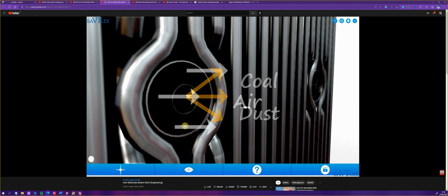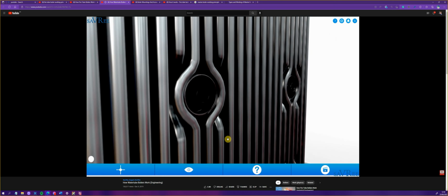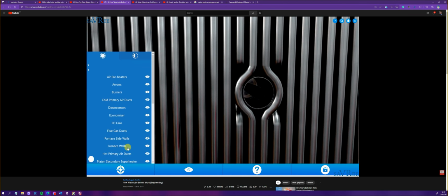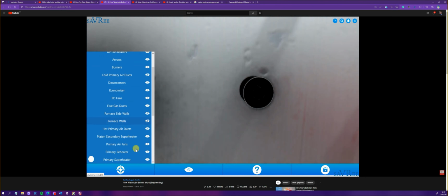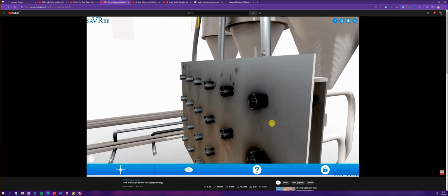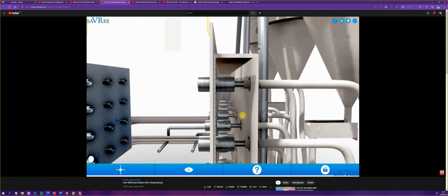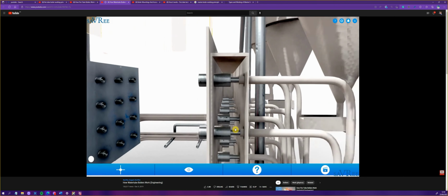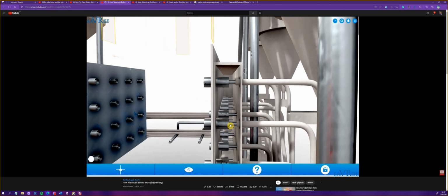And around the outside here, we're also going to blow air in as well, which is going to ensure that we get very efficient combustion. Behind these tubes, which I can now hide, is actually what they call a wind box. So we can see it's coming in like so. Our wind box here allows air to fill up this space, and the air is then pushed into the furnace. We have two main air systems associated with the water tube boiler. That is primary air and secondary air.